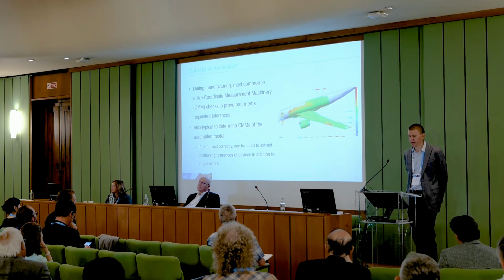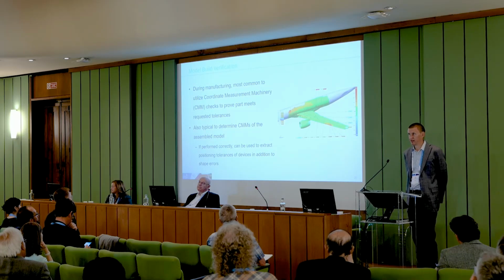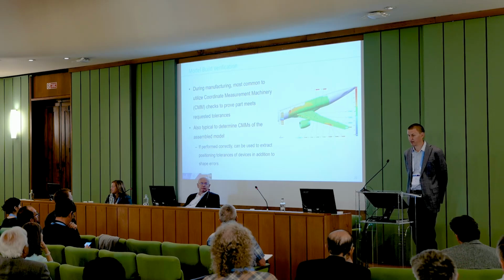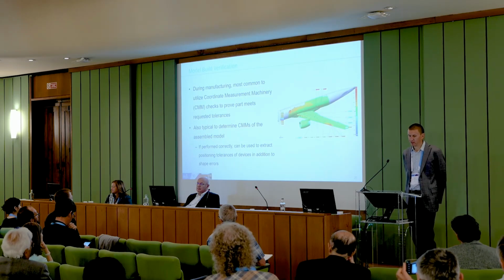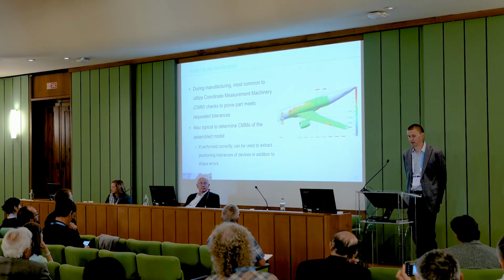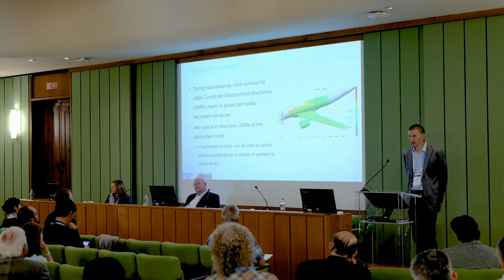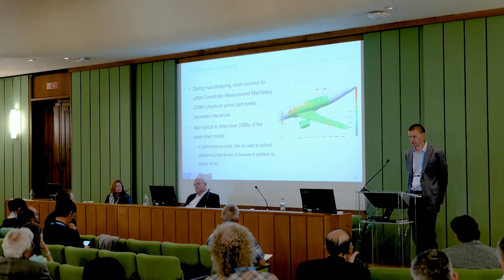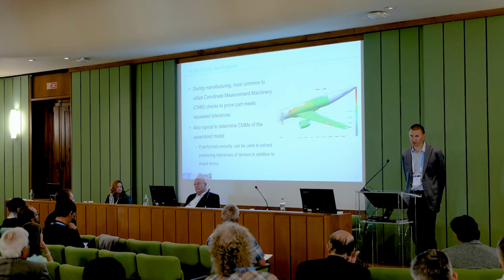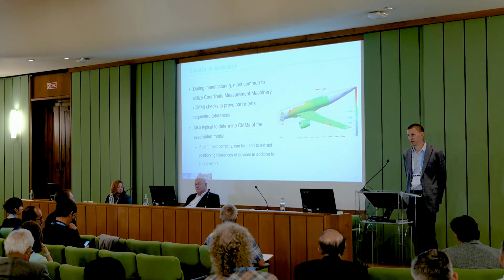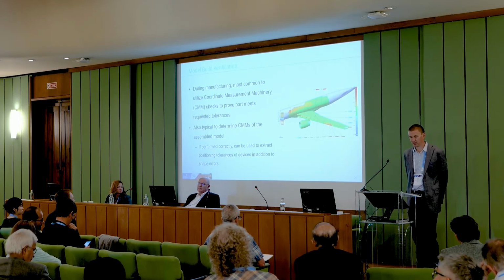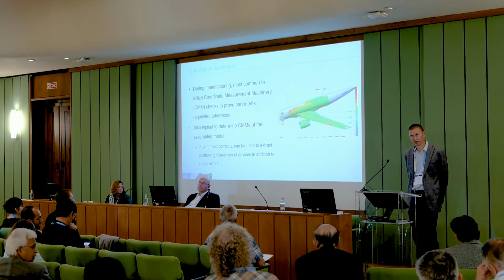Build verification is another step. So again, the idea here is to verify that the parts that you had manufactured, you provided drawings for, you provided CAD models for, get built per that drawing. So during manufacturing, it's most common to utilize coordinate measurement machinery, CMM checks. We've seen a variety of how this is done throughout the ecosystem. There are people that just CMM the individual parts. We've seen quite a few ecosystem participants CMM the full assembly, which is pretty dang helpful. If it's done correctly, it can be used to extract the positioning tolerances that we actually care about, but that gets pretty dang complicated pretty quickly.